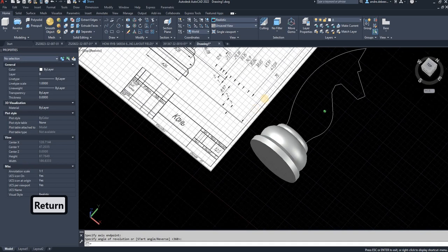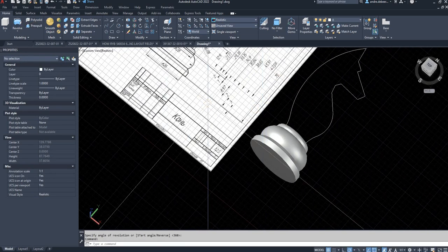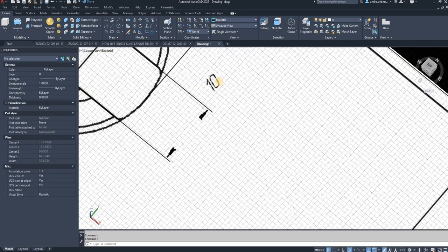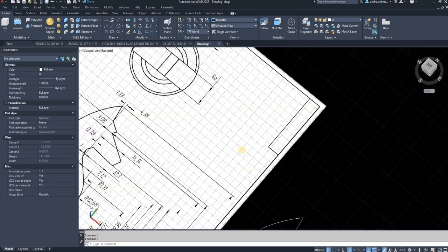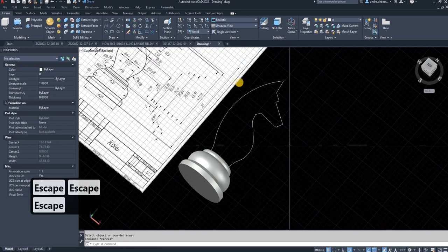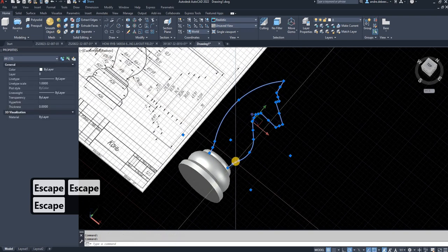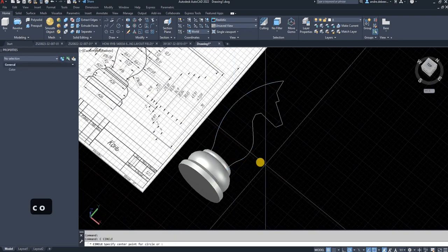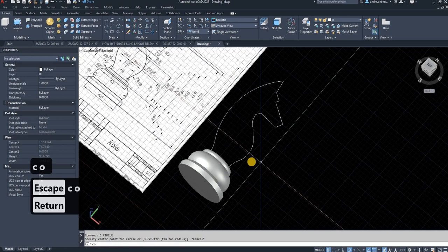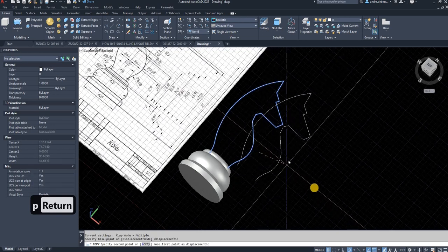So the next piece is going to be the horse's head, and we're going to just check the dimensions, and as you can see here, it's shown it's 10 millimeters wide. So I'm going to use press pull function. I'm going to move, or just to make a copy of this, with CO, enter, and use the previously selected lines with P, enter, right click to accept the command.